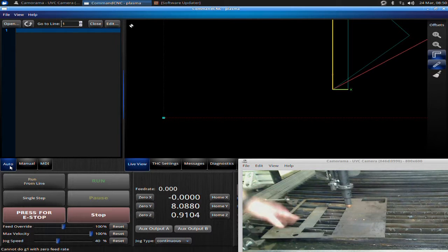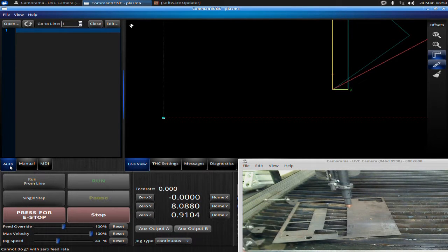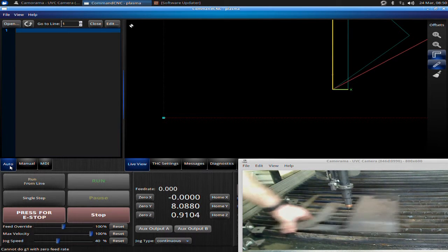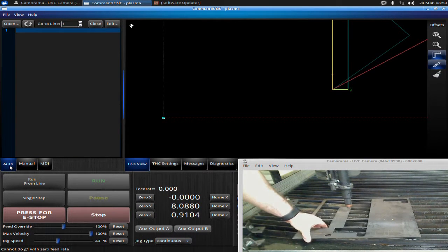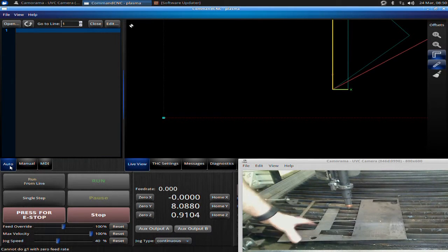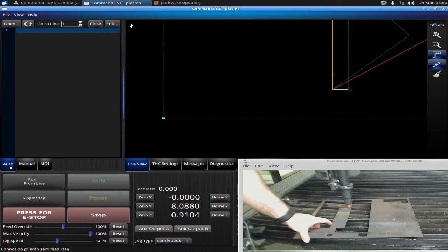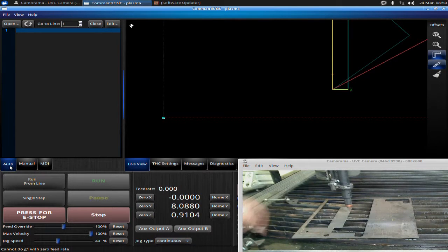One way that's obvious that you're kind of out of luck is while you're cutting, your plate moves, okay? If your plate moves and you really don't have any set position where it was before, you just have it sitting on the table, and your plate is moved, you're kind of out of luck. There's no way to get it back in the right position. And that's why we have these material stops here.